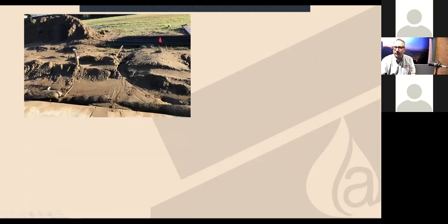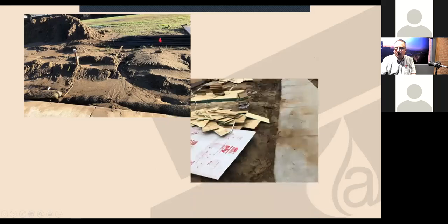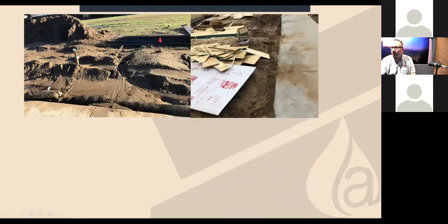You can see the silt fence there. That's failure, probably mostly in managing the site, but also understanding the flows. You can see erosion coming across there. Of course, you got bad site management happening in that picture here. Here is actually, it doesn't look like a fiber roll until you look really closely. It's what we call Pancake Waddle.